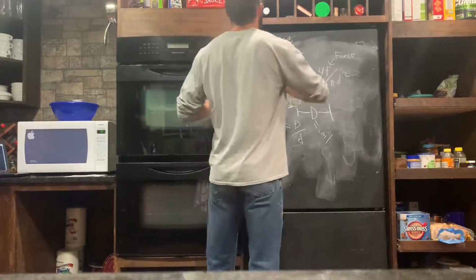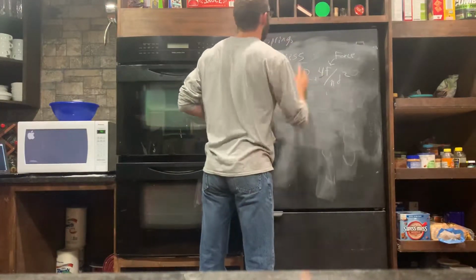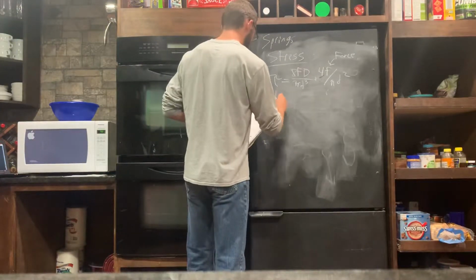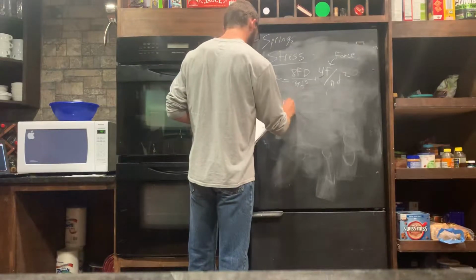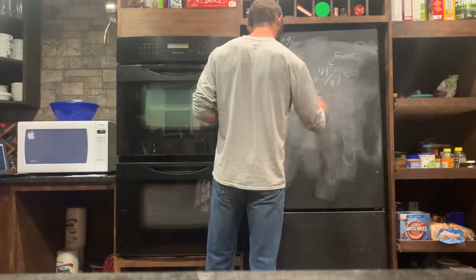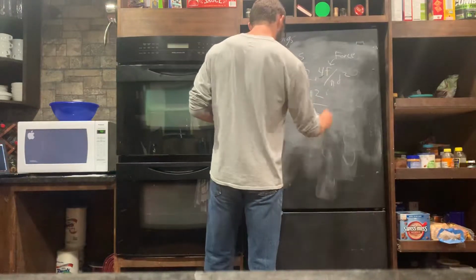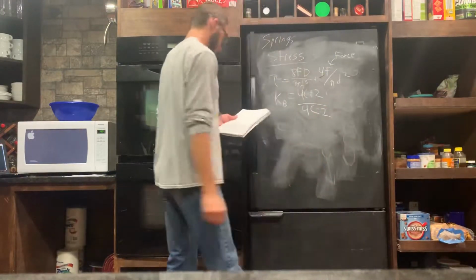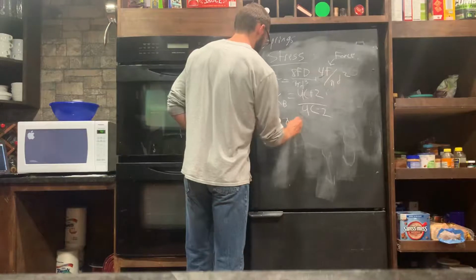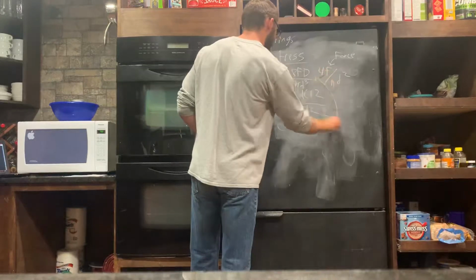We may also have a different force in the spring due to curvature. If we do have a curvature effect on the spring, we're going to have this new variable, KB, and that is going to equal, going back, we're going to be using the spring index here again. And we just plug that in front of the new KB times this.